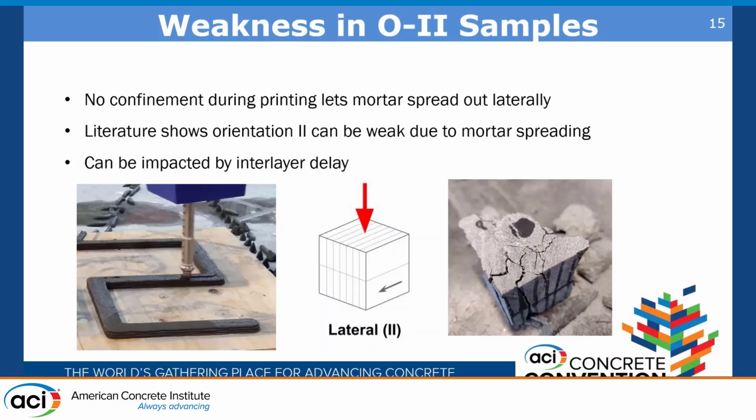This is especially important for our setup, because the way our prints occur is that one layer pushes down slightly on the other layer as it is being printed. This is extremely useful to have high interlayer bond. As you can see from this sample, if there was any failure between the layers, we'd see some striation along the layer path, but we're not seeing any.